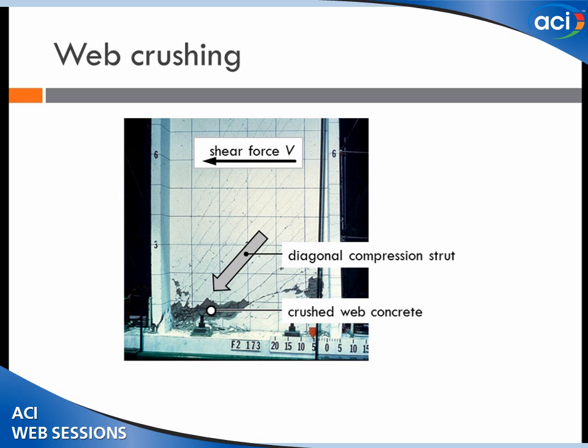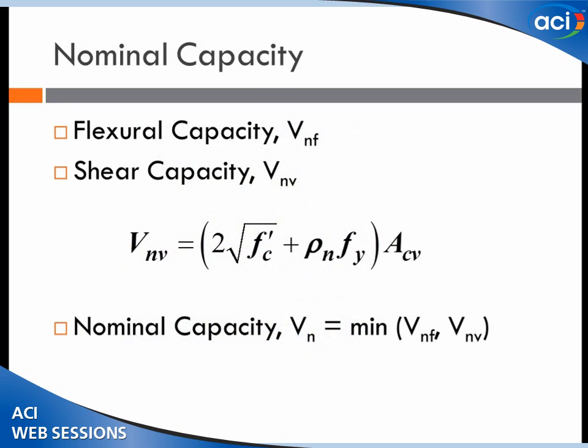Maybe there's a need to revisit some of these factors here as well. But fortunately through Gene's work, this was all tuned to work at about 1.5% drift ratio. It's probably quite safe for designs today.